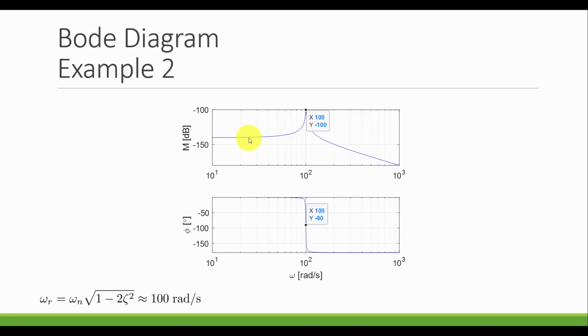So let's say the problem we're facing at the moment is we must drive this machine at 100 radians per second for one reason or another. Maybe it's in line with other machines that must rotate at the same frequency, say on a common axle. But the whole machine resonates at that frequency. So we have a design problem: we don't want to operate near the resonant frequency. We could change the input frequency, but let's say that's not an option. So what would another option be?